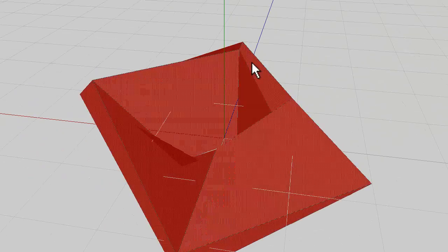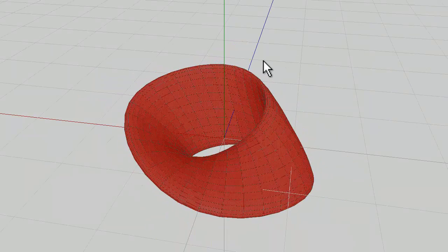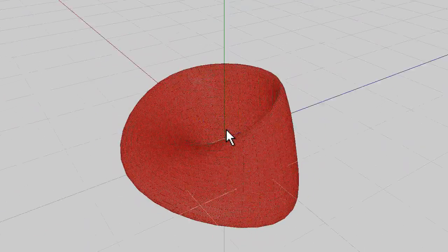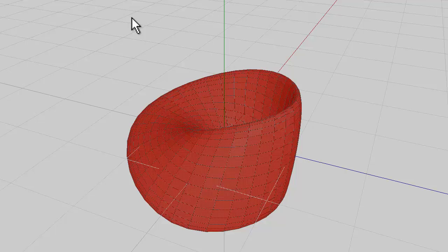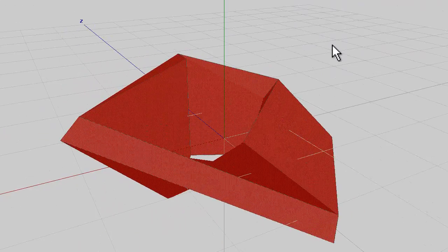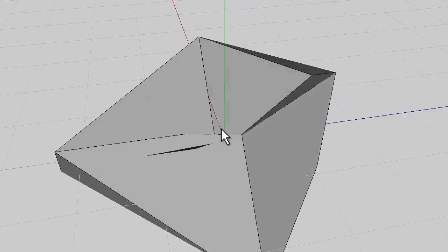Now at this stage, if I select the entire object and smooth it a couple of, 3 times, you can see that I have got this Mobius strip shape. If I want to go back to where I was, more than one Control Z undo step, do Control Z and hold the Alt key down, and then press the Z, and you can go back a step at a time. Okay, so that now has taken me back to where I was.